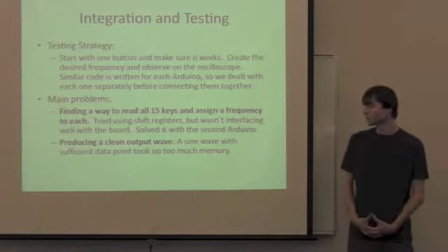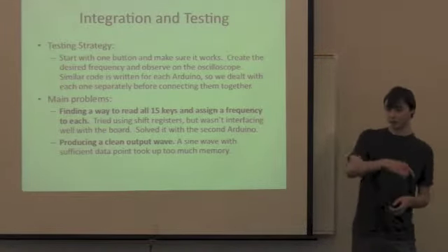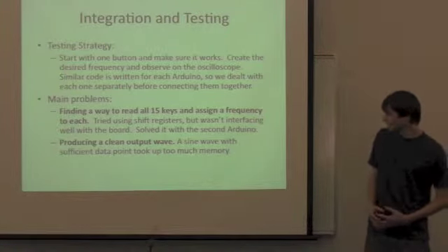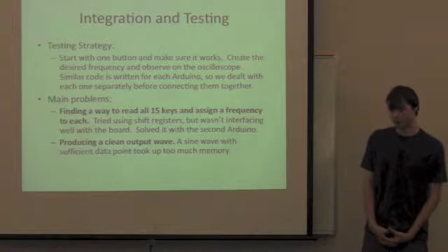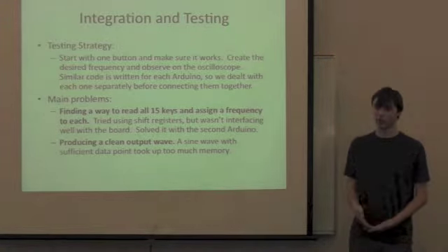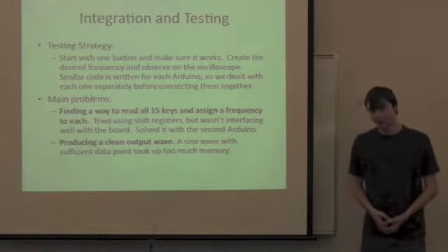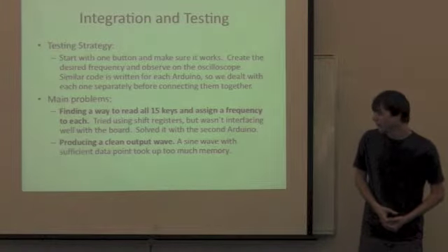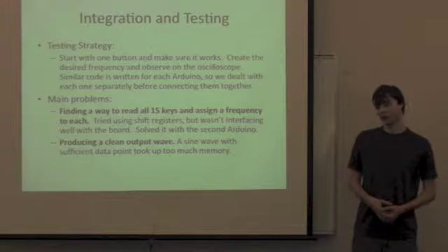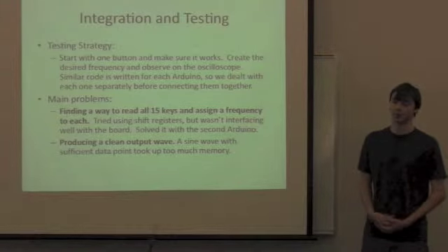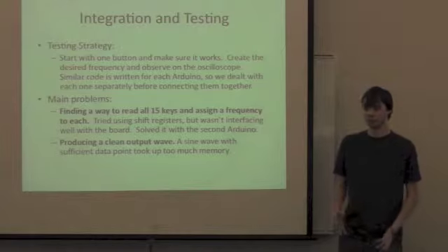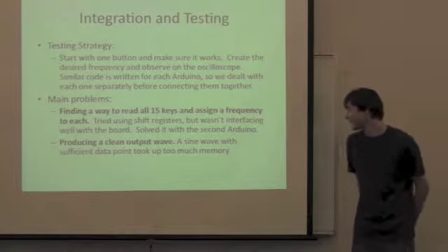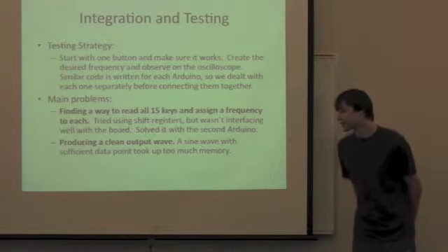Instead, we interfaced with 2 Arduinos, and we actually have them sending data across from each other and combining the data for the output. This is a problem when you're using square waves, though, because you can't get clean chords with it. All of our code would work for combining 2 notes, one from each Arduino at this point, but without a sine wave, it sounds really choppy and it just kind of cuts in and out. We can demonstrate that when we get up there, but we do have all of the necessary software to implement multi-button functions. We just don't have enough memory space, or our Arduino clock doesn't run fast enough, so we actually capped out our microcontroller there. So I guess now you want to move to a demo?